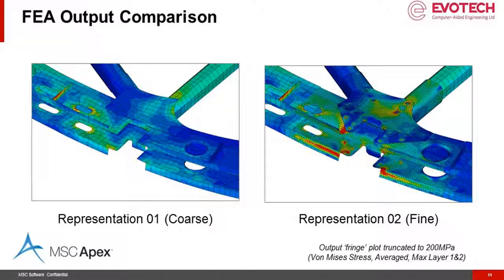And again, depending on what we're trying to do, whether this is a loads model for screening, understanding load path, or a fine model for understanding detailed joint response and maybe fastener loads, bypass, or bearing bypass load between fasteners, we've got a good definition of that representation, and Apex is able to handle both model representations in a single model.